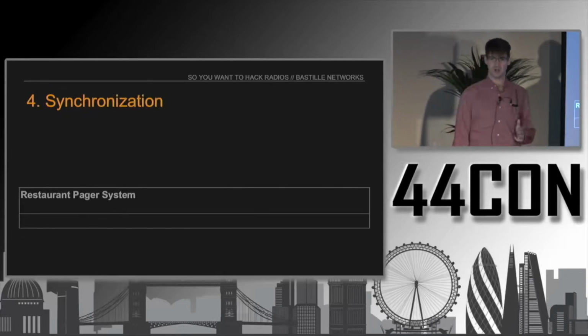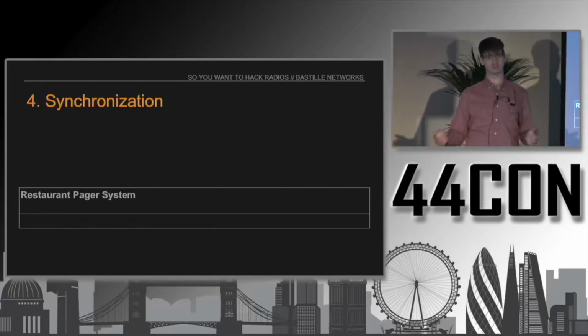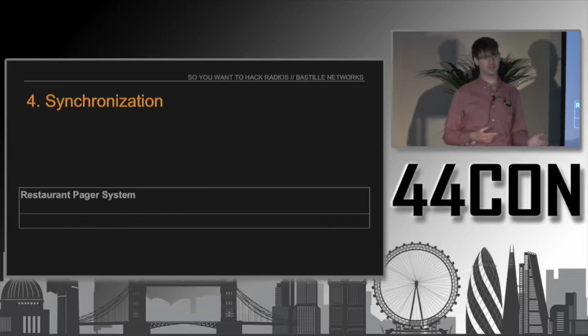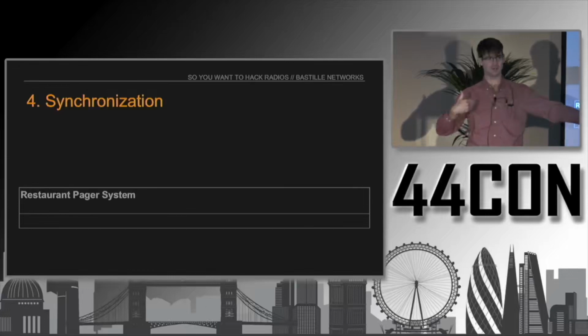For synchronizing, we were able to theorize, by looking at it and identifying the preamble, the 1000 1000 repeated pattern. Had we implemented this in Python rather than using URH, you'd just process that bit stream, look for that pattern, and then grab the next n number of symbols and work with that.